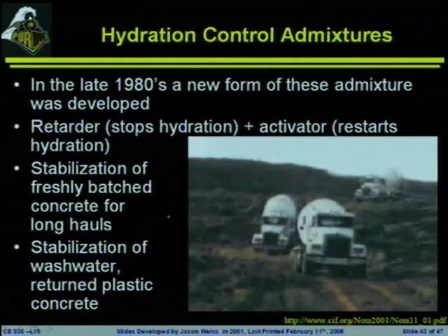Here are some concrete trucks. They're roaming throughout the west of the United States looking for a place to discharge their concrete. They are several hours away from a particular plant. This, I believe, was about an 8-hour haul to get the concrete out there. The idea is when the concrete was being mixed, you throw in the retarder or the stabilizer into the system. When it gets out on the site, they would add the activator to start the overall process.